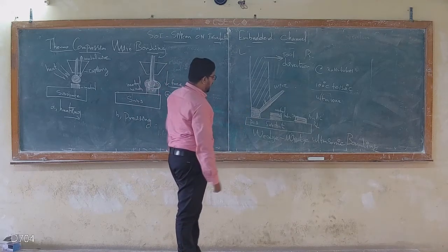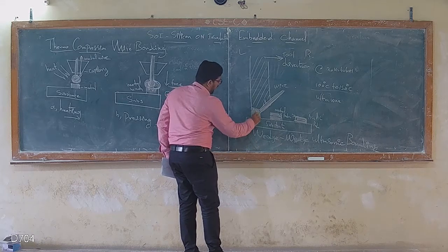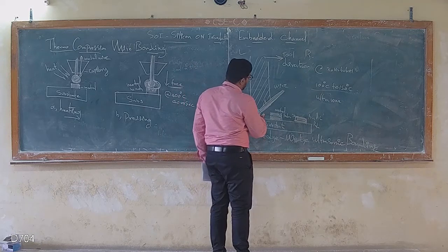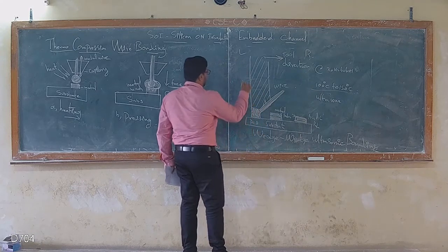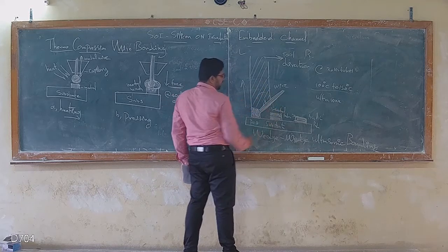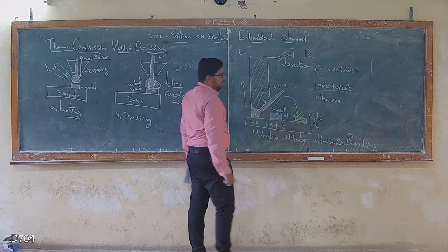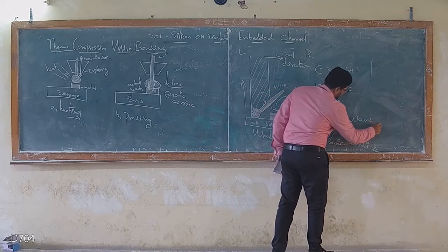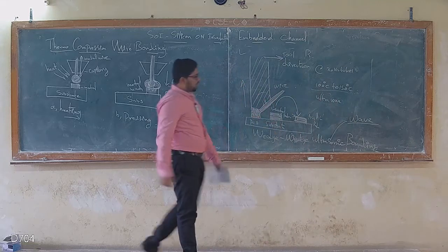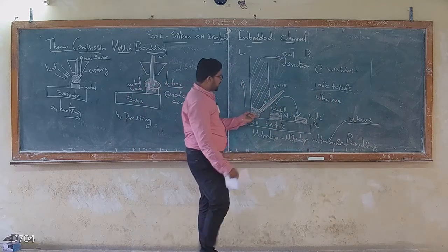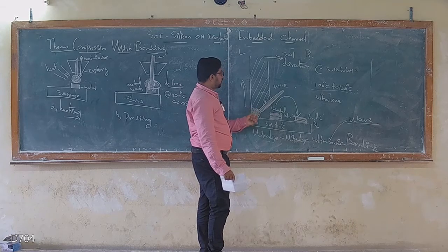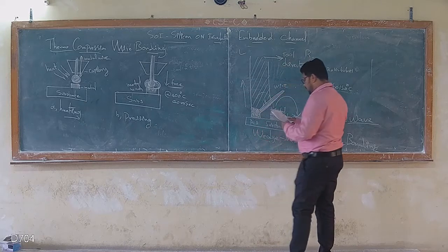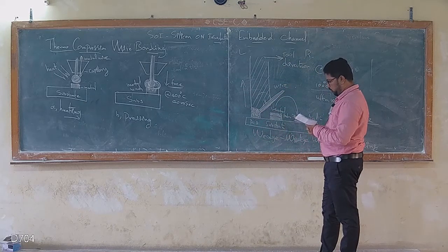This vibration makes sure of the reaction between these two metals and forms a metal bond. Once this is completed, the tool is lifted up like this and moved to the next metal. In that way the metal bonding is taken care of because of the ultrasound wave. The wave has its own mechanical vibration, and that mechanical vibration creates the local bonding between these two metals. Not only the mechanical vibration, it also has its own force of energy, the mechanical force of the tool.